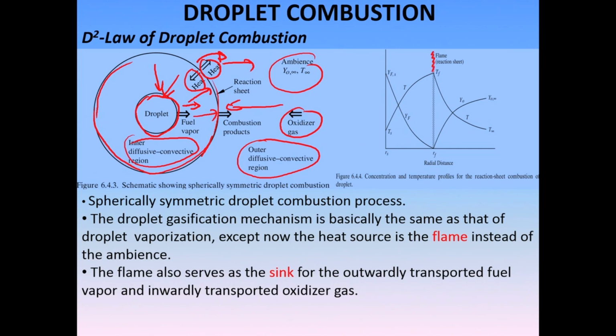If you look at this flame front very carefully, there are some interesting things that you will observe over here. One particular case is that YFS is the concentration of the fuel vapor near the droplet surface, right. This fuel vapor concentration slowly decreases as you go towards the flame front, because it becomes exactly equal to 0 there, since the fuel vapor is completely consumed by the flame front. A similar thing you see for the oxidizer. At the far field, the oxidizer has some concentration, which is Y0 infinity. The oxidizer concentration also comes down and gets depleted over here, right.